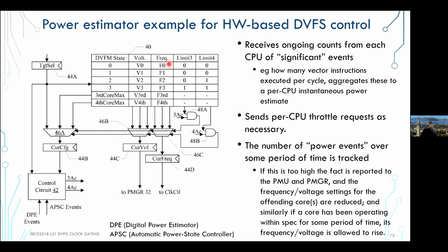your system. And then it also depends on the number of cores that you can afford to run on that system for those voltage frequency settings, right? So for example, if your voltage frequency setting is too high, you may not want to run all 4 cores at that, because you're going to be heating up the overall power limits of the whole package. And so you want to limit that. In certain settings, you can only run 3 cores or 2 cores or 1 core, right? And then those are kind of these limiters that tell you for a certain application, a given voltage frequency profile, I can run this many cores maximum, right?